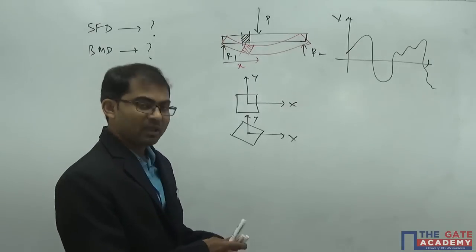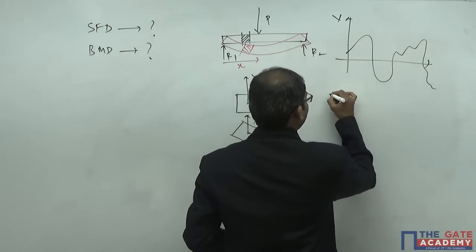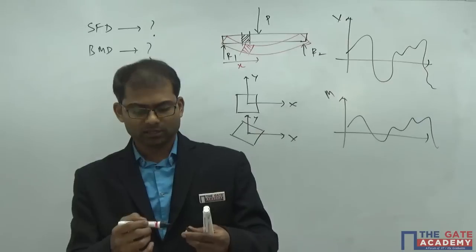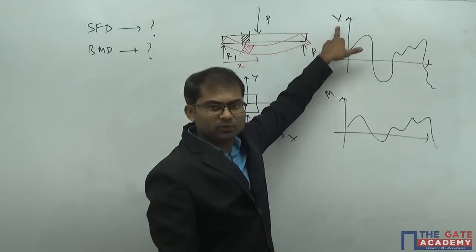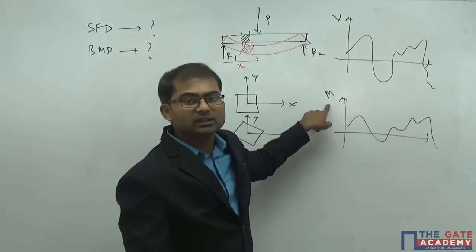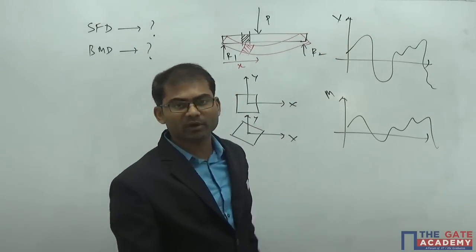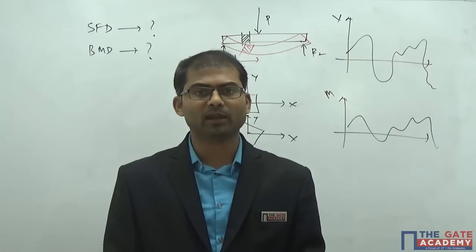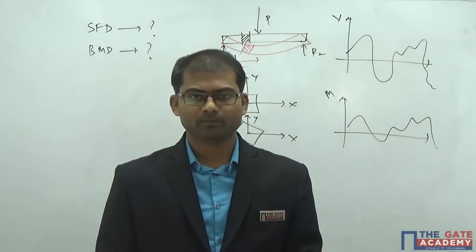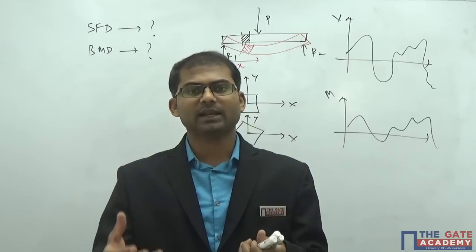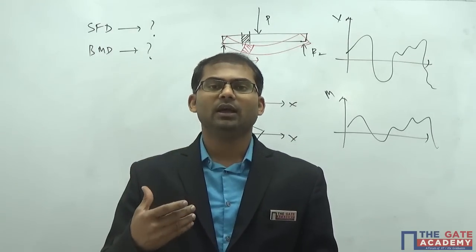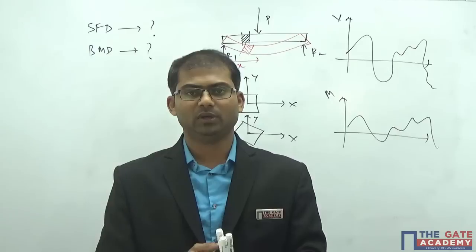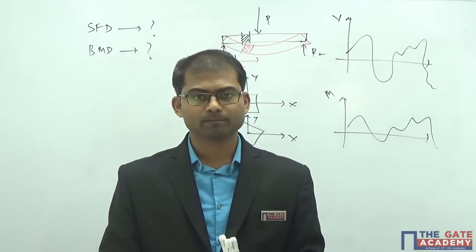So in the bending moment diagram, I basically find out this induced value of the bending moment along the length of the beam. So using these two results, we're going to find out shear stress induced inside the beam using the shear force diagram, and we're going to find out the bending stress induced inside the beam using this bending moment diagram. So that is the importance of drawing the shear force diagram and bending moment diagram in the subject of strength of materials. Without understanding or knowing this technique of drawing the shear force diagram or bending moment diagram, we will not be able to evaluate the stresses induced inside the beams or the members which are actually experiencing bending.